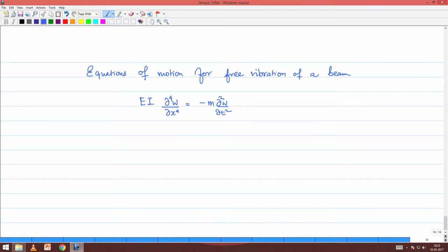Now, let us look for a harmonic solution, just the same ideas as we did in acoustics. So, once we say that I am looking for a harmonic solution, w(x,t) will now take the form W(x) times e^(i omega t). So, omega is the associated frequency, right. So, we are hoping that we are able to find some non-trivial solution of this system, which is of this form. w(x,t) is W(x), which is a function as yet unknown, times e^(i omega t), right.